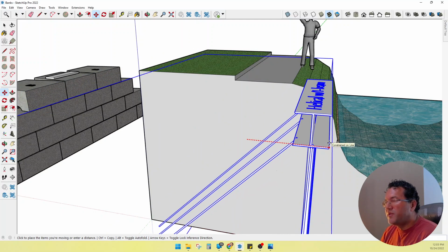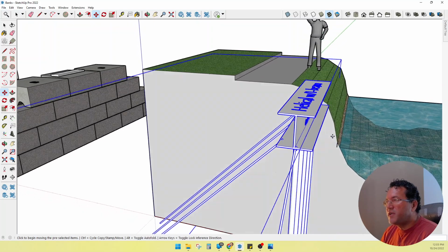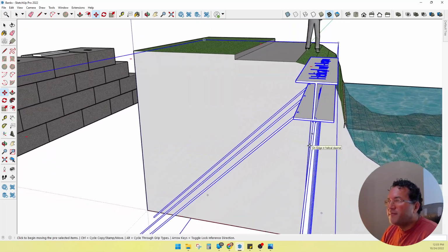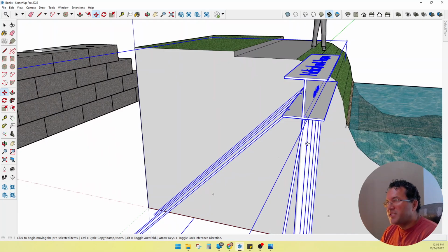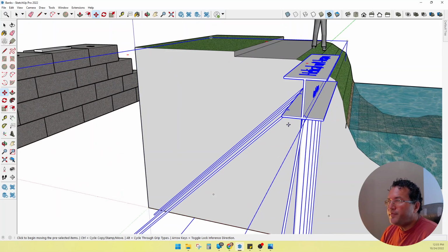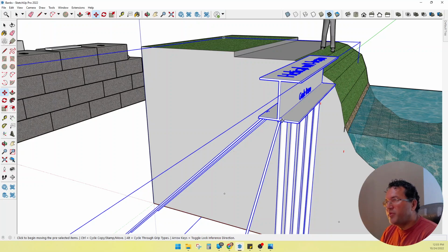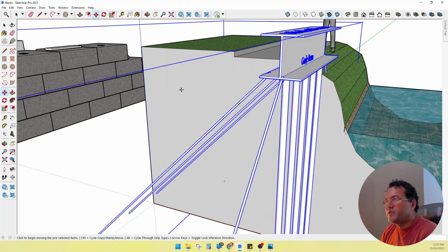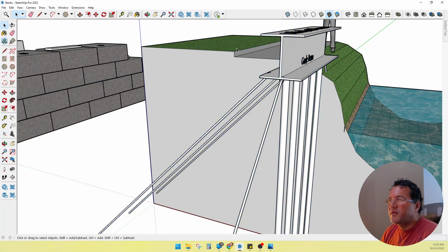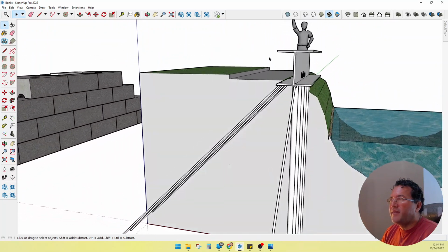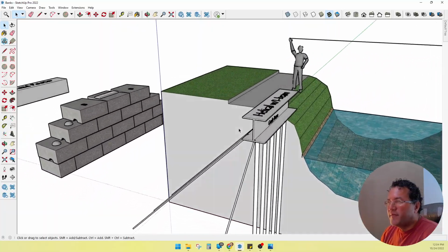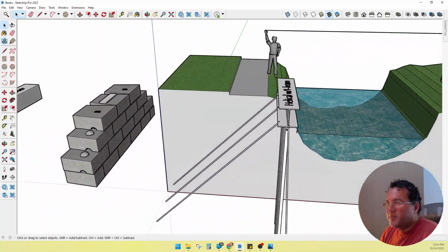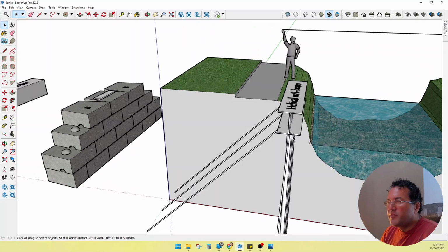We've gone up to within 6 inches of the side of the waterway. The amount of excavation required is very minimal. Last time we did it, we actually put the bottom of the grade beam right at the bottom of the bridge, so kind of like that, right? And then the bridge set on top of that. So that's a pretty neat way to build an abutment.